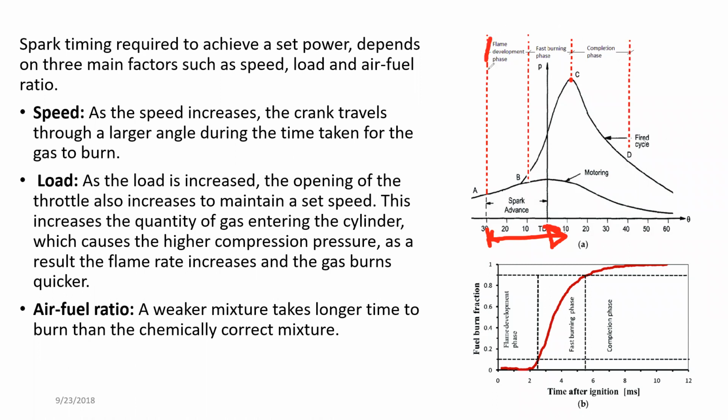So this has to come a little bit back, which means the ignition has to be reduced, because it's burning faster. So these details also have to be fed into the system.